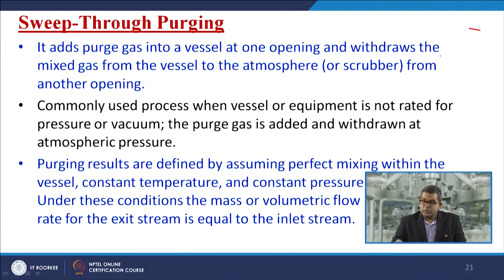Now, usually what we do is, let's say this is my vessel. From one end we draw the vacuum, and simultaneously we introduce a certain quantity of inert gas over here, and continuously we draw the mixed gas from that stream. Because we have to maintain a certain pressure difference, we draw the vacuum in the first stage, then we close it, then we introduce a certain quantity of inert gas, and continuously we draw the mixed gas from this front.